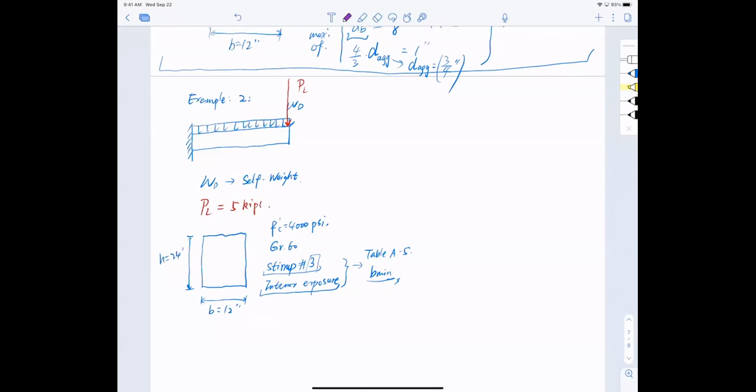So quick question for you. Now, pay attention. I'm being a little bit tricky as Bob, right? So I'm gonna put a reinforcement in it. In the common case, the simply supported case, I'm gonna put my reinforcement at the bottom of the section. Is that right? Yeah. So in this case, it's a cantilever. So should I put my reinforcement here, or should I put my reinforcement at the top? At the top? Why is that?